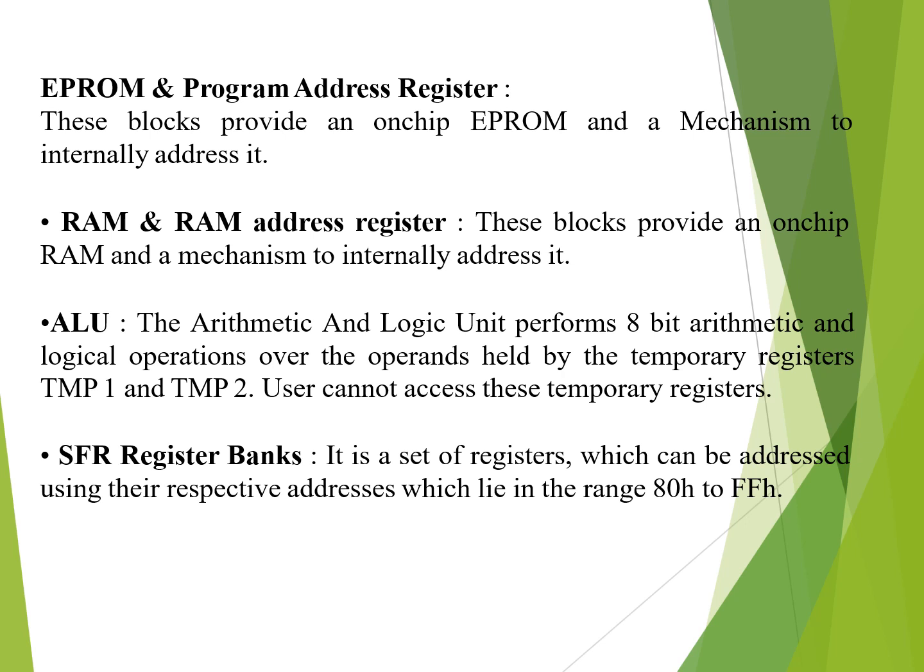The next one will be the ALU, which is the heart of the 8051 microcontroller. The 8051 is having an 8-bit ALU, which stands for arithmetic and logic unit. This unit is responsible for performing the arithmetic operations. It is able to perform logical operations as well. It receives the operands from the two temporary registers, temp1 and temp2, that are available within the 8051 controller.